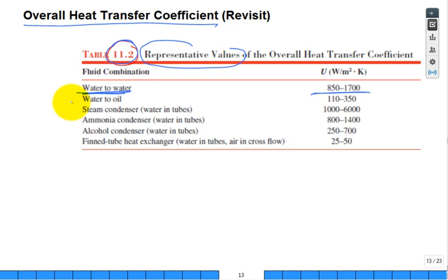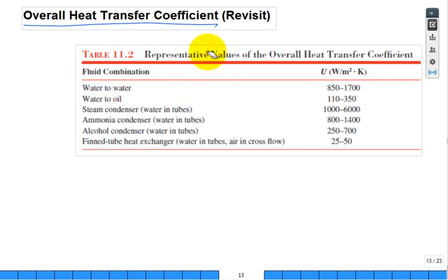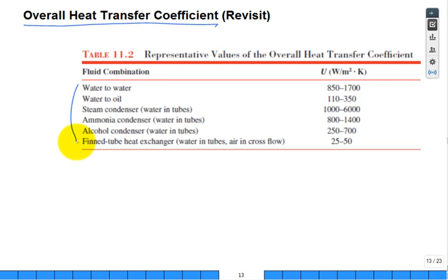And when I talk to students doing a senior design project, often I'll go to something like this in our fluids book or heat transfer book because they got some calculations that are way off. You know, it's like, hey, I made the calculation, I have water-to-water heat transfer, and I have U that's 10 to the 6. Really? Well, it should be around 2,000 or lower, unless you have some really exotic behavior. So anyway, this helps you. I think this table is helpful. Let's continue on.